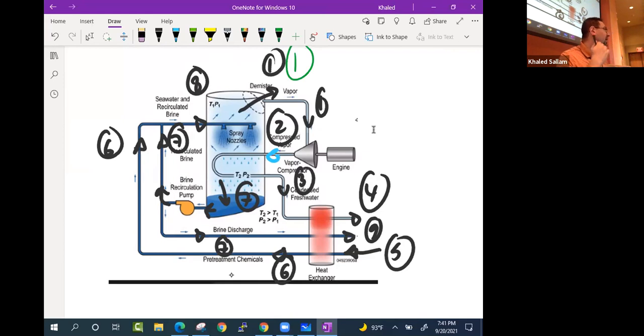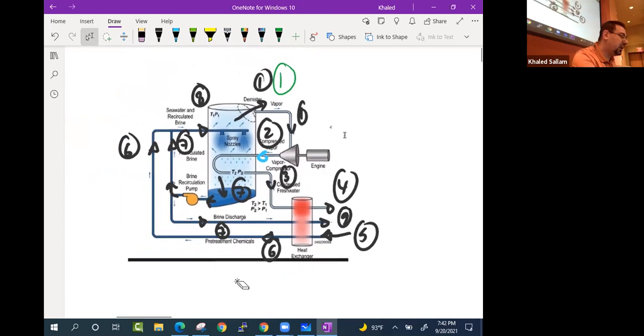It's not like the boiler feed water pump, which takes the water from condenser pressure at 0.07 bar to 220 bar. This is just a circulating pump. So if you want to be super accurate, you can make it 7 and 7.1 or something, just a little bit of change in the pressure, but it's not going to be a big deal. Okay.